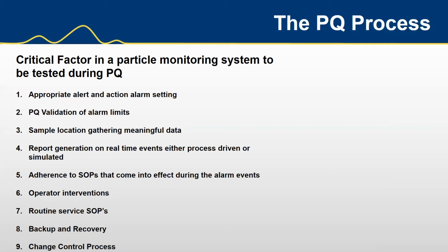You want to look at the backup and recovery of the system and any change control process, making sure you don't make any changes to the system without going through a change control process. I've seen so many systems where we've installed, verified on site and validated the system as it is. Six months later, the customer will call us and say, hey, we've got a problem. What's that? Well, the system's not acting like it should, and we need you to come help us. I said, well, have you done anything or changed anything on the system? Oh, well, IT did put in a new server.